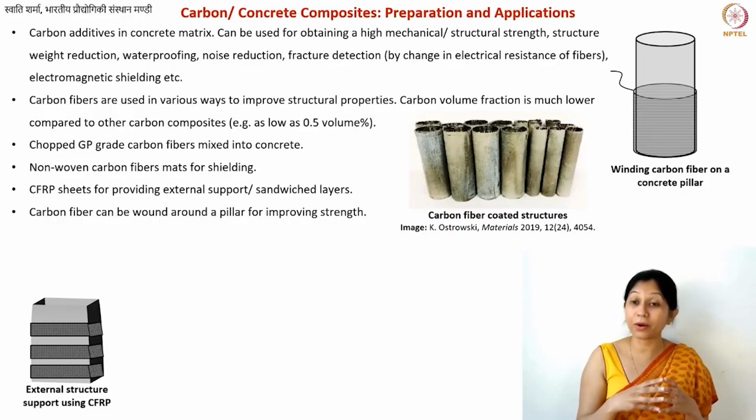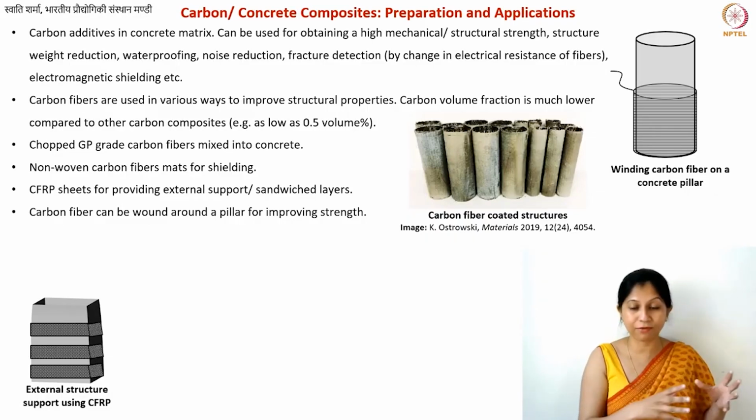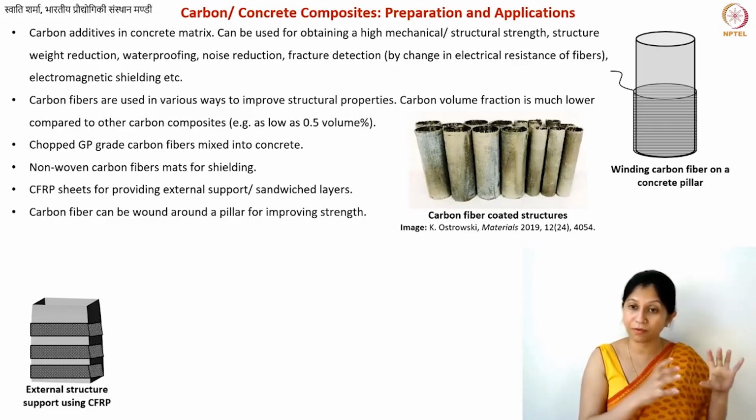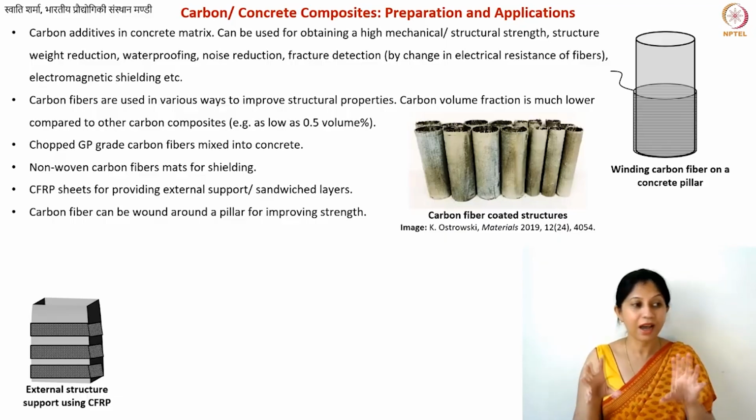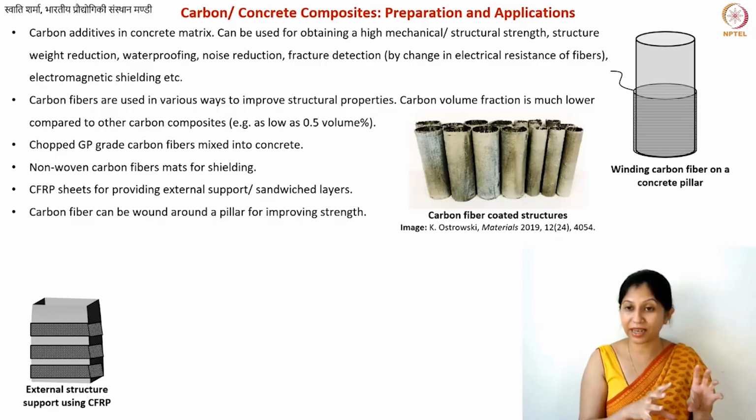These are probably going to be thick ropes. So there you have to do, remember from our mechanical property testing lecture, carbon fiber mechanical property testing. You need to have a good tensile strength in these fibers. Again, modulus may not be so important. Rather, the ultimate tensile strength is more important, and you will most likely choose PAN derived or isotropic pitch